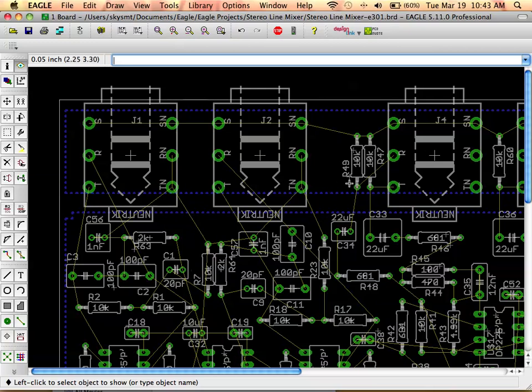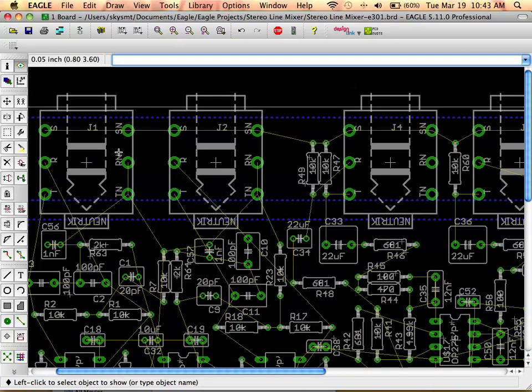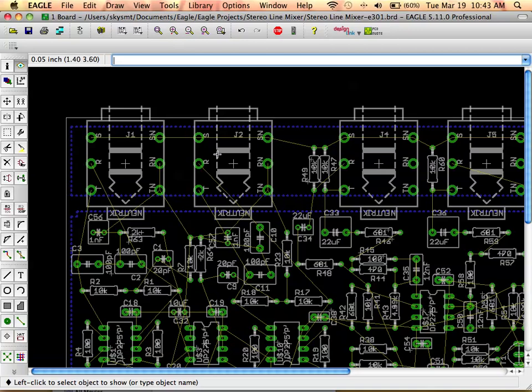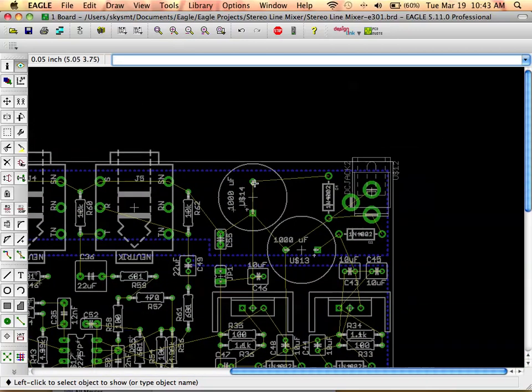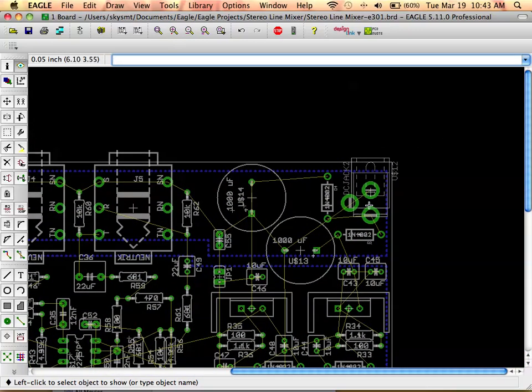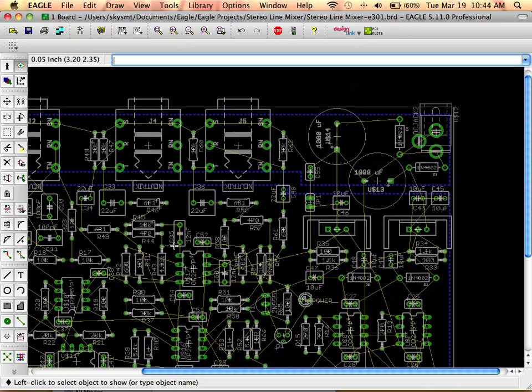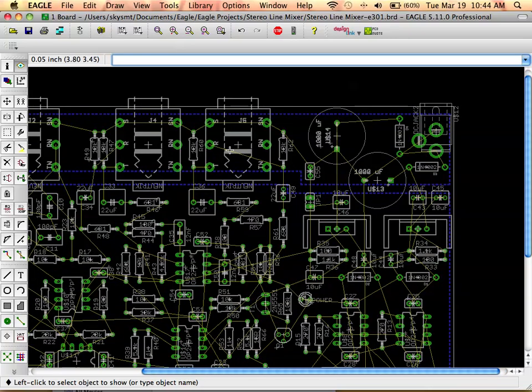So you have a separate ground pour, and often this is done with a chassis. It's just done with the metal on the chassis instead of having a separate ground pour. This board wasn't going into a chassis, so I sort of simulated having a chassis with this ground pour in the back, and then forcing that to have to travel back out of the power input jack and back down to the wall, instead of running through my circuitry first, or having the chance to flow over the ground plane of my signal circuitry at all. It's not allowed to get over there.